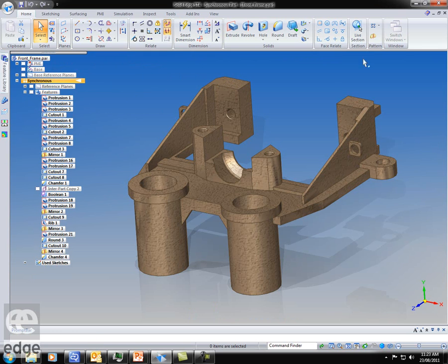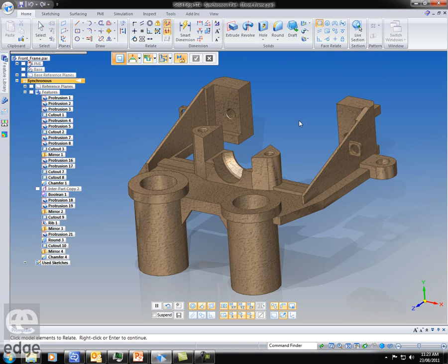The relationships were down here. They've now been moved into their own toolbar. So if we wish to place a coplanar relationship on, just do a singular line. So I want to place a coplanar relationship on that face and that face. You'll notice that the first face I pick is in bright green, which is the seed face.